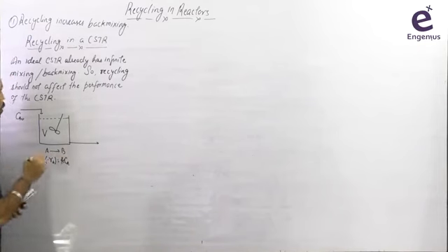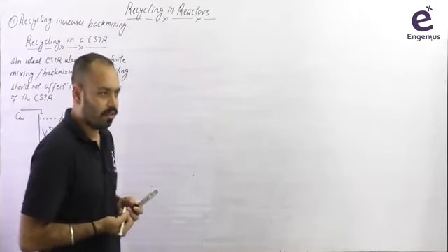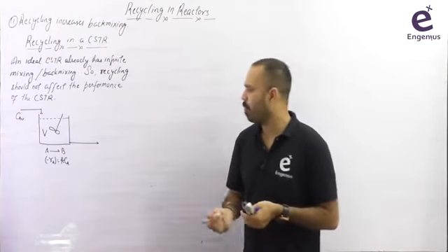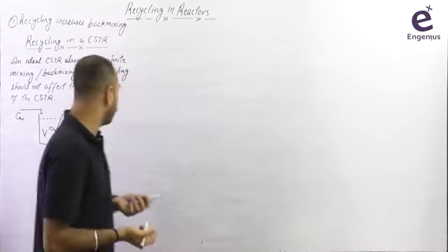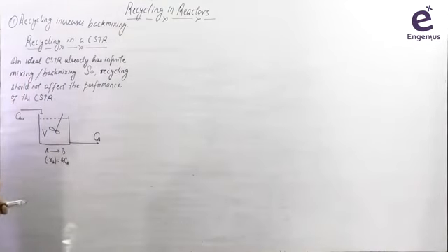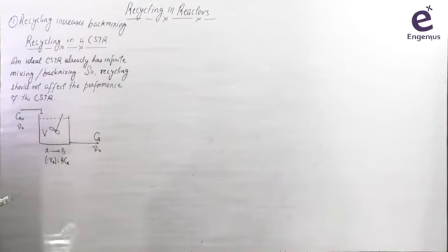And of course, whenever I am proving anything, it is always easier for me to prove things in case of a constant volume reaction system. So again it is a constant volume reaction system also. You are having some exit concentration Ca, volumetric flow rate nu naught. Let a first order reaction take place. What is the performance right now? What we have studied is a CSTR without recycle, right? This is a CSTR without recycle.